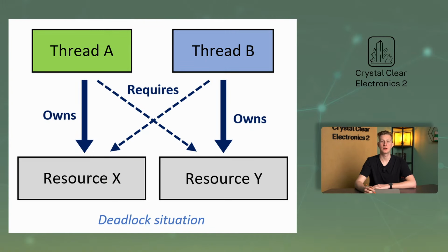I should note that the use of mutexes can easily lead to 2 or more tasks becoming stuck. This situation is called a deadlock. In this case, both tasks are waiting for the other and neither can move on. This can happen when there are several shared resources between the tasks and they want to request additional mutexes. In the next chapter, we will cover this in more detail.